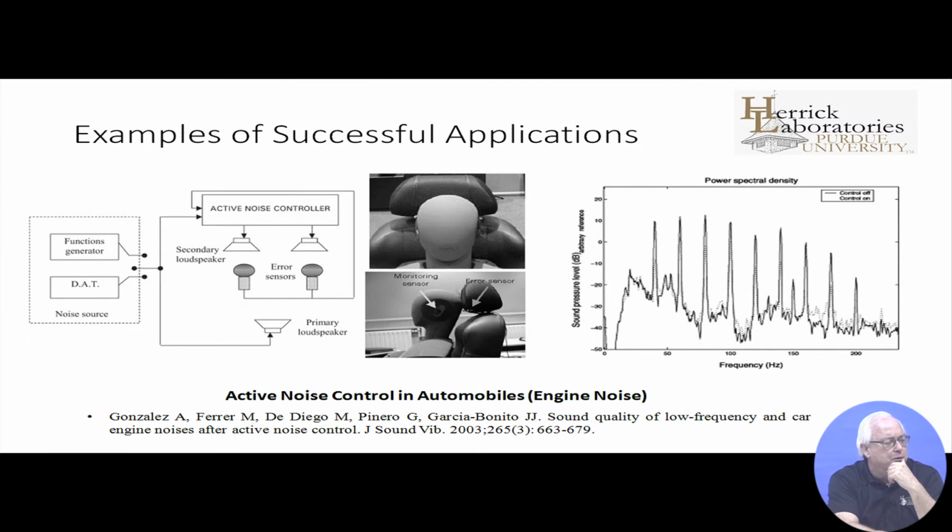And then the issue really becomes one of where you are sensing, because it would be nice if you could put error sensors in the driver's ears, but the driver may object to that. So the error sensors are not placed very close to the head, and as a result, sometimes the performance is a little bit variable, and also things change as the head location changes, because the transfer functions between the loudspeakers and the points that you're trying to cancel also change.